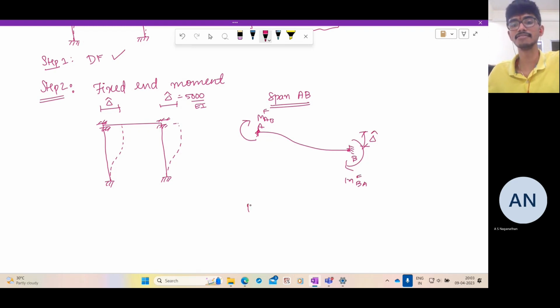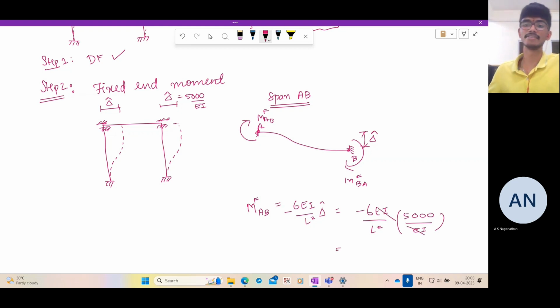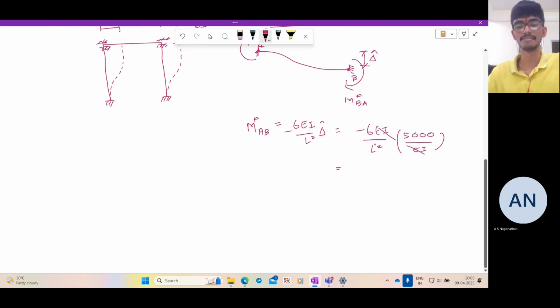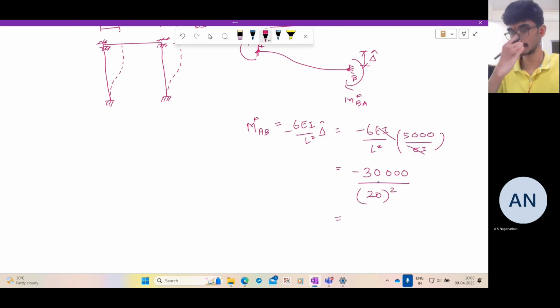So by the slope deflection equations, MABF is equal to minus 6EI by L square delta cap. But what is delta cap? It is 5000 by EI, so EI gets cancelled. You get minus 6 times 5000, which is minus 30,000 by L square. L is 20, so 20 square. So this turns out to be... Let me check. Something is...